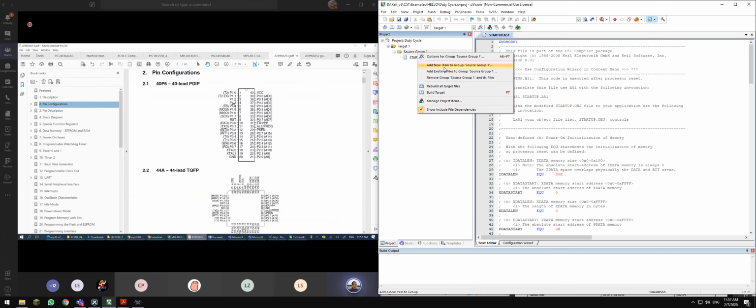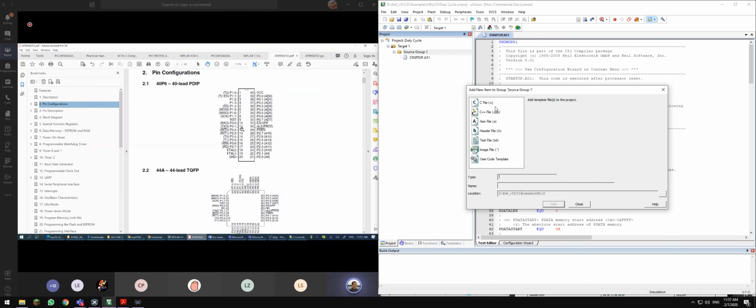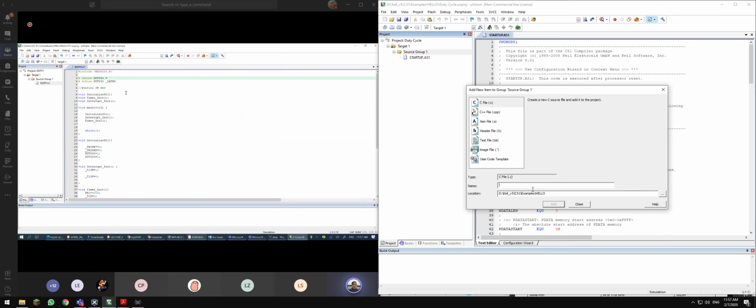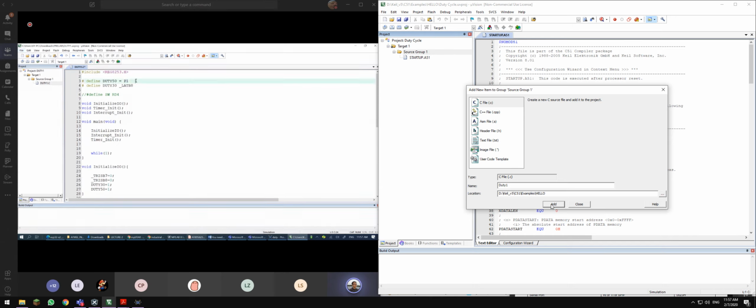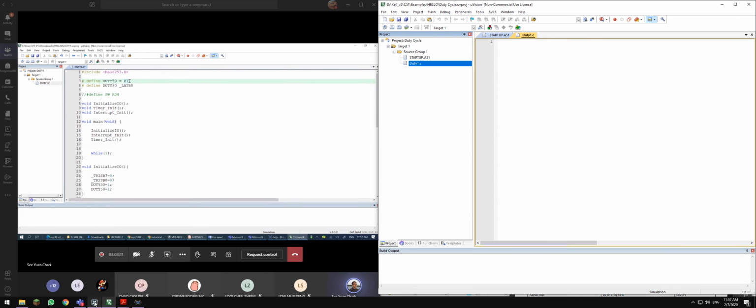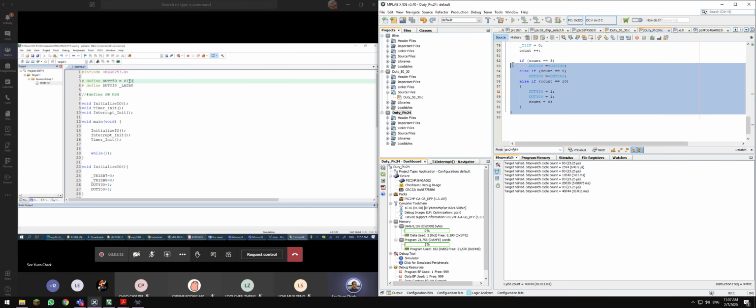Instead, if you look at the AT89S8253, the pin configuration is just port 1.0, 1.1, 1.2. They are using ports. So to define this, the way of writing is just to write P1. I enlarge this for you. Port 1. Now I need the sbit, bit 0, for example.